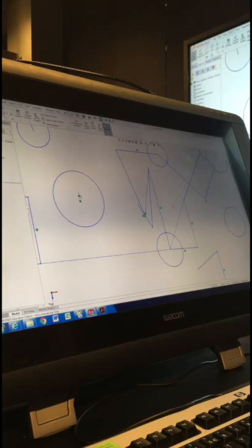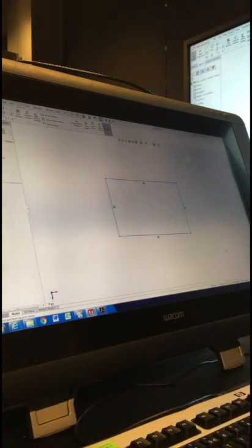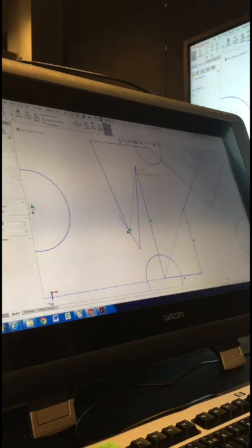They're not necessarily big issues, but if I'm drawing, let's say I'm going to draw a shape like this that I'm going to turn into 3D, what I don't want to have is another little line like that tagged off the side. All right, that's going to cause issues with my sketch when I'm trying to dimension and extrude and things like that. So as much as we can, we want to have an enclosed sort of space. So if I delete that line, you can see how that one goes back to a normal sort of thickness. And same with those two. Once I delete those, all of a sudden this area is a nice enclosed area again.